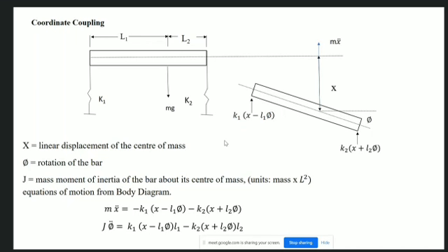But if it doesn't happen so, that K1 and K2 have such values that whenever the deformation takes place, the upward forces exerted by these springs have a resultant with a line of action which is different from the downward force applied, then apart from the translation, a couple will be formed by these two forces, and that will try to create a rotation.